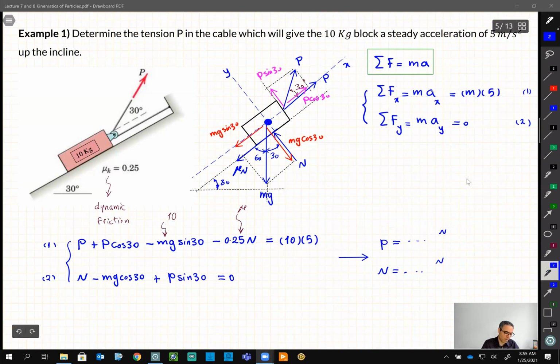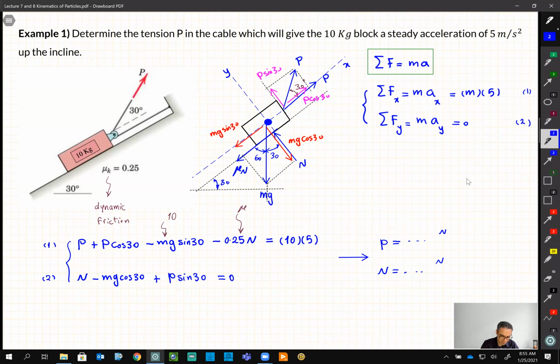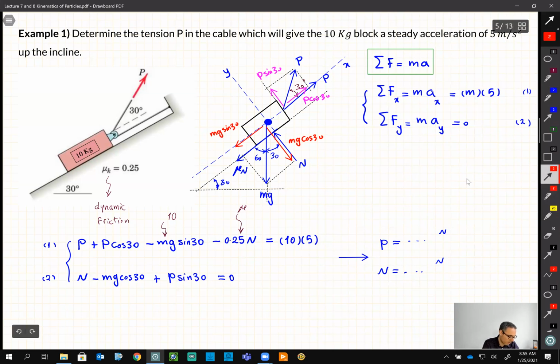Yeah, thank you guys. I'm glad sometimes you guys help each other. So we have two forces because pay attention here. We have like P here, right? And then we have the pulley. So as a result, this one also is P because the question didn't tell anything about friction around the pulley. We assume if this is P, another one is also P. Okay, any other question? So yeah, there is tension on both sides. And what else? Nothing else.